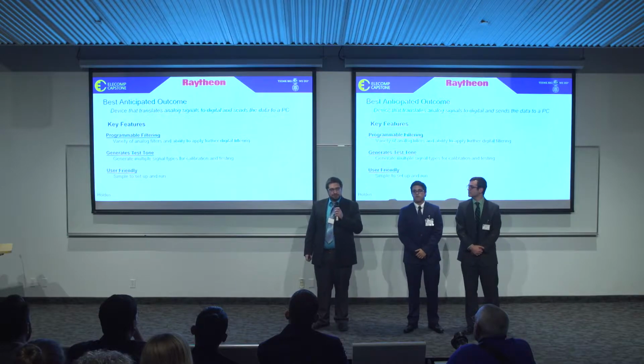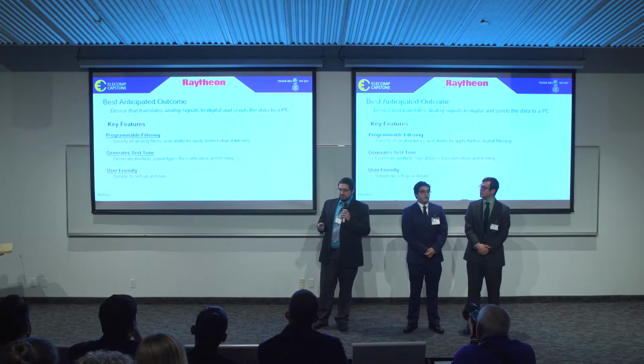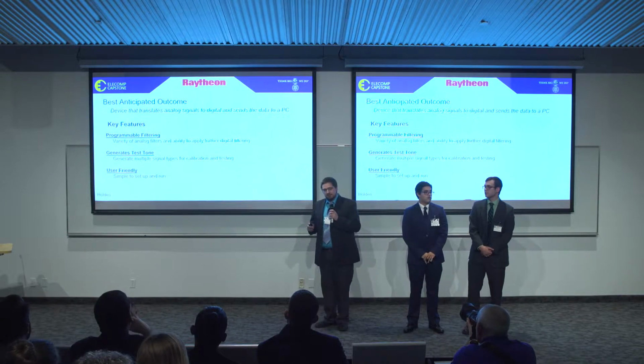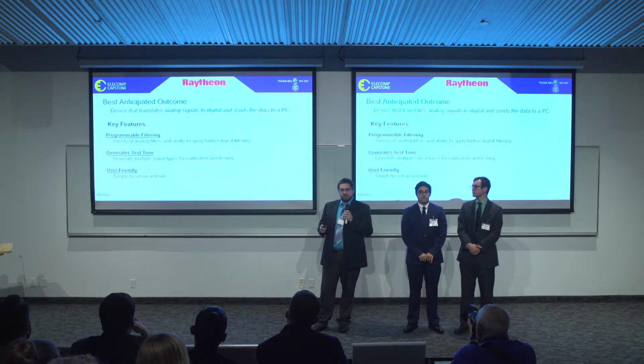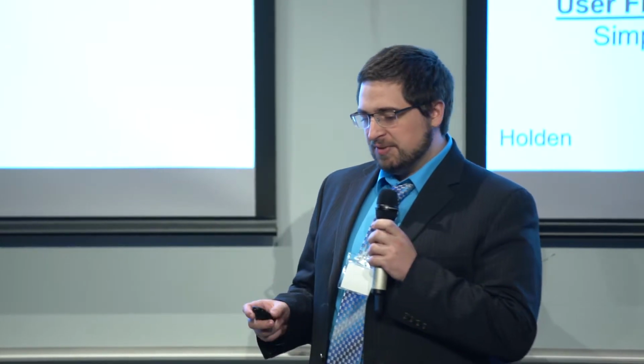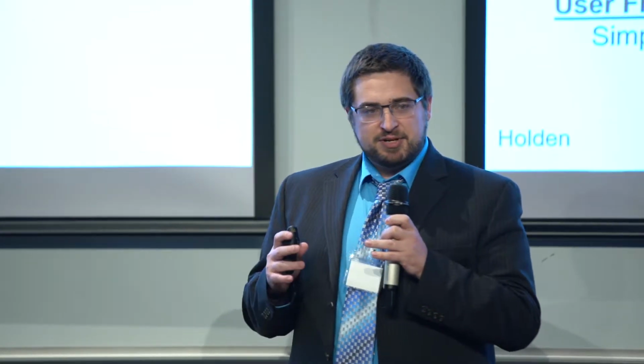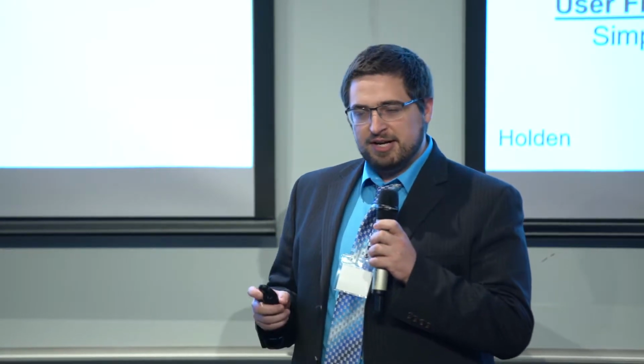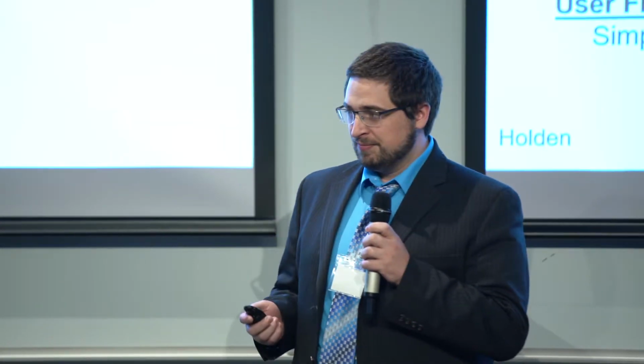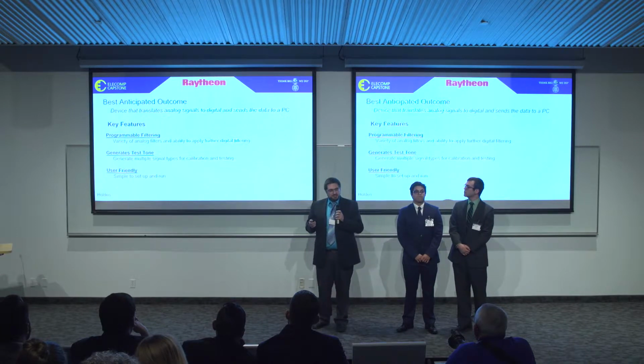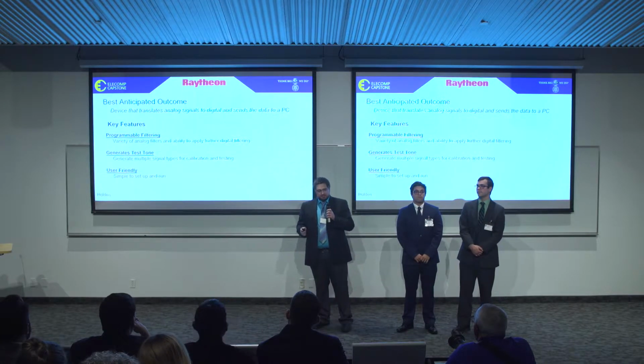In service of this goal, the best possible product we could make is one that follows all of the design outcomes specified by Raytheon, namely the ability to take analog voltage signals from a hydrophone, convert them into digital data, packetize them in the processor, and send it off to a PC for later analysis with more software that we are making. In addition, it needs to be simple, easy to use, and flexible.